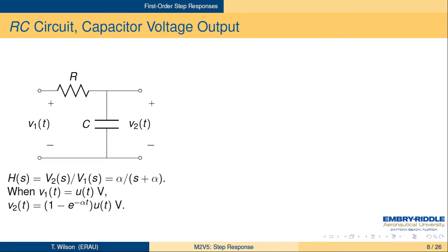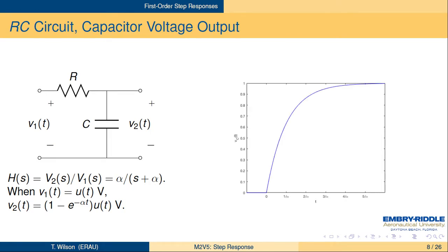So you know what this is going to look like. It's a 1 minus exponential form, so it starts at t equals 0 with a value of 0. There's really a constant 1 there, and then there's a minus e to the minus alpha t. I didn't plot the separate components, but those add up to that standard step exponential shape of a 1 minus exponential. Okay, so let's say somebody gives you this graph and says, how would you find out the alpha?